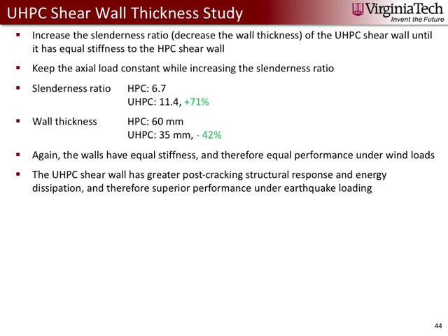And the way we can think of this is we take a building with an HPC shear wall, and we want to take it out and swap it for a UHPC shear wall. So none of the loading conditions are changed between these two scenarios. So we need to keep the axial load constant on the shear wall, not the axial stress, as this changes with changing thickness.